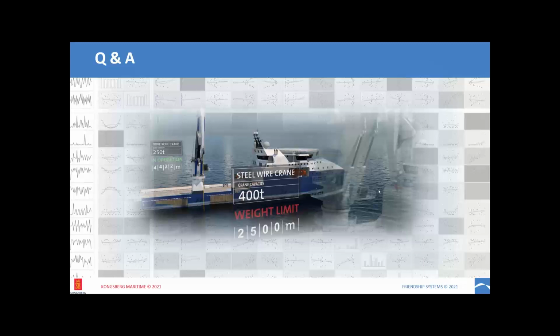I have a few small questions that I think I can also directly answer. Parametric deformation: is it possible to apply it on a model generated in NAPA after importing it in CAESES? Yes, that's possible. You can export geometries in NAPA in IGES format and import them in CAESES as a surface model. We also have some cleanup functionality, because sometimes the NAPA models have a lot of surface patches and they need a little bit of repair to have a clean geometry. And then we can apply all these deformation methods that Heinrich showed to these imported models.